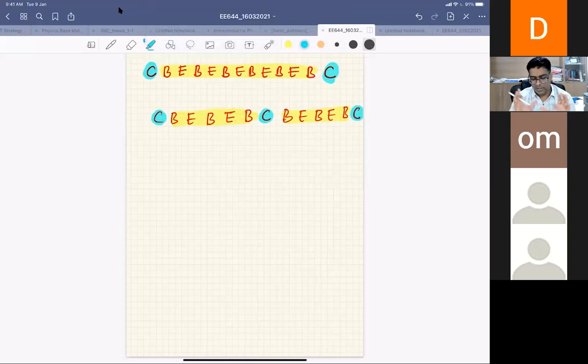But if you compare the first design and the second design, here I have made emitter fingers and base fingers, and also one extra collector in between, so that collector resistance is not compromised. So this is how you draw, lay out the bipolar junction transistor to handle very high current. Emitter crowding is the bigger concern.